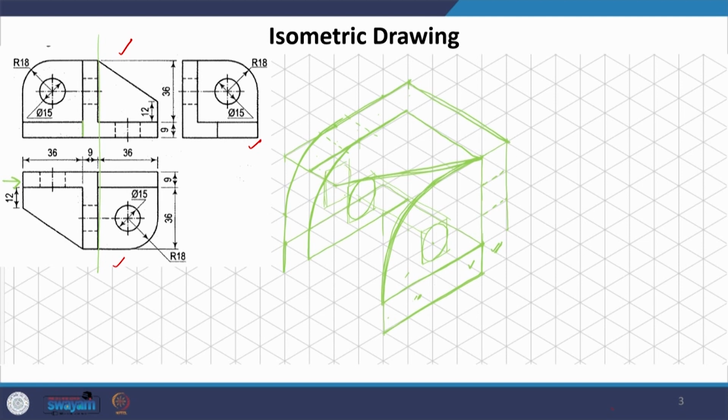I am drawing it dotted because it might or might not be seen, and now we can see that it is actually not seen. So, this is a hollow. What we have done is taken the front part of the elevation from the front plane to the back plane, and we see that the edges actually match. This is a continuous curved surface. So, we will see it like this.